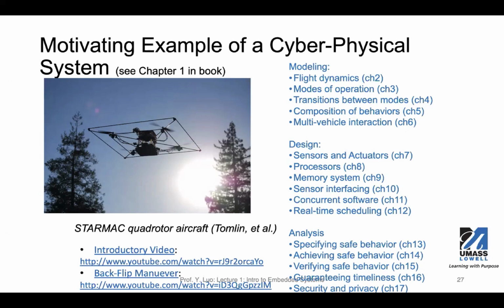First, how do we control the flight? As you can see here, this is a Quadrotor, which means it has 4 rotors at each corner, and you can control the speed of each rotor, which produces different thrust pushing downwards. You can adjust the thrust force by changing the speed of these rotors to perform different movements, for example, moving forward, backward, or even flipping over. So the control of such flight is very complex itself.